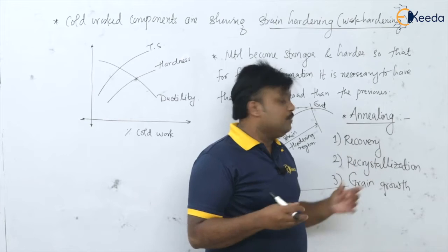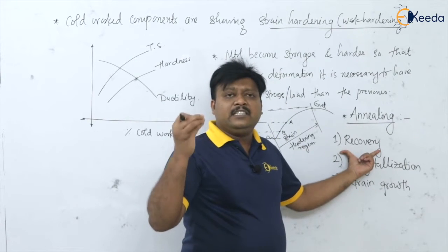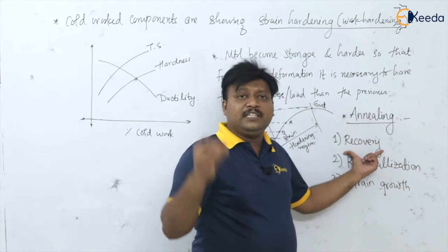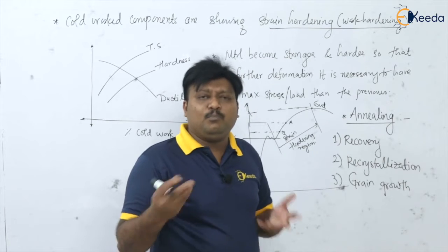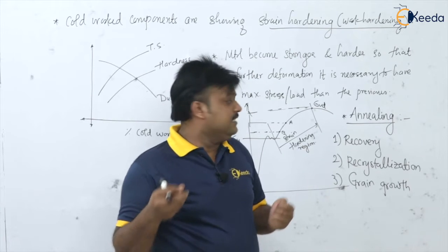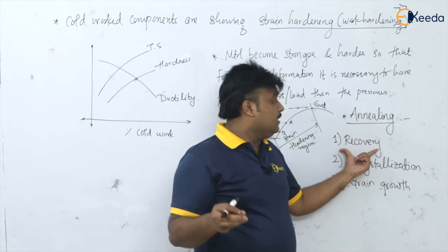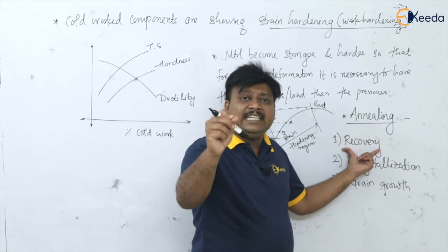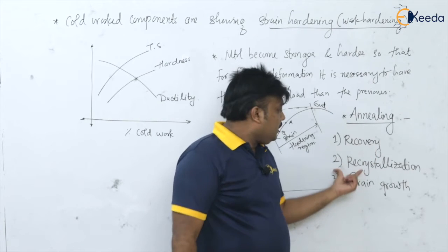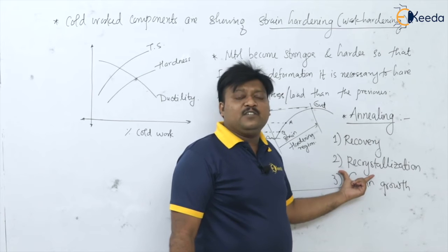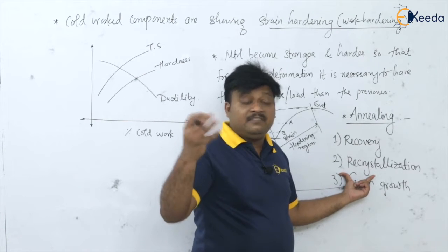So temperature is fairly low and we are removing the residual strains or stress in the material because of the working, to recover properties like electrical conductivity and thermal conductivity, with a little bit of increase in ductility. That is the recovery. We have talked about recrystallization, the formation of new strain free, stress free, equiaxed grains.